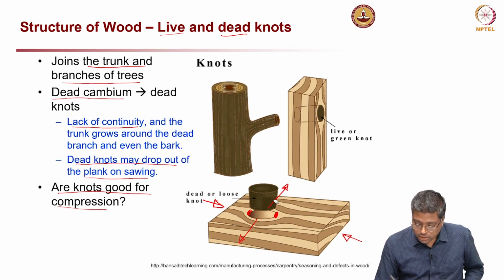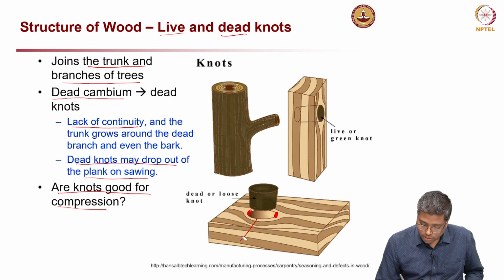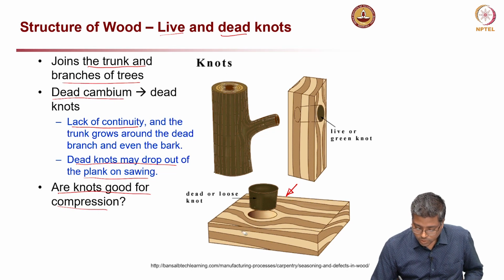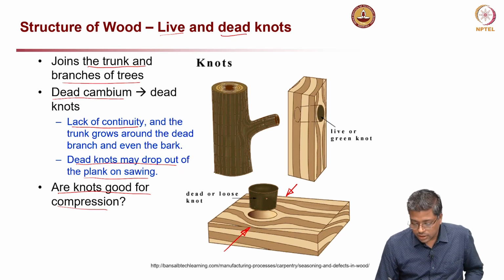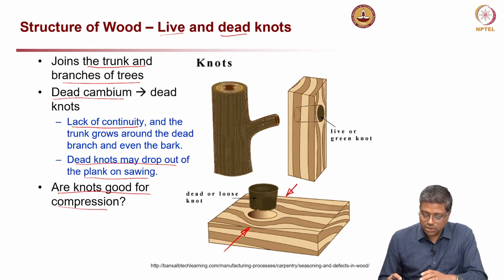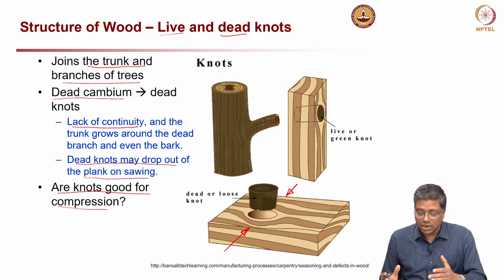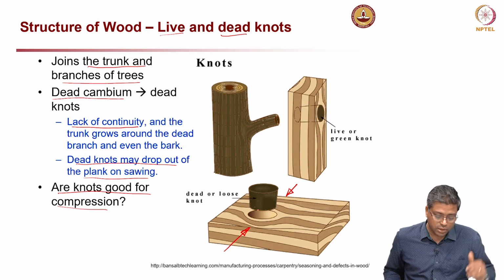That is one thing. Now, if I apply a load in the other direction, let us say I am applying the load in this direction, then also there is a compression and it might push the knot out, but again you might experience a stress concentration. Depending on the direction it might not affect much in this direction, but in the other direction which I showed you earlier, it will definitely have some impact on opening up or cracking of the wood along the grains or between the grains.